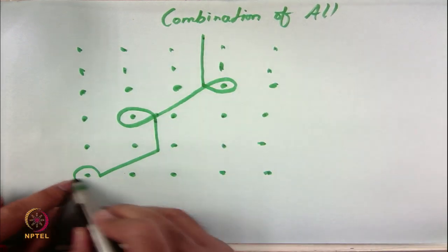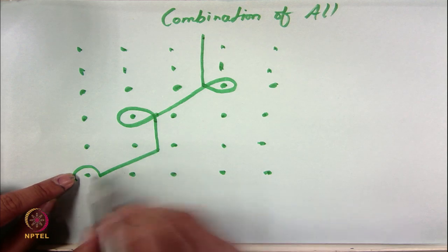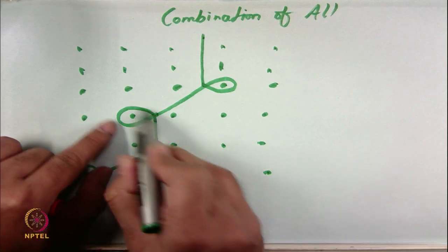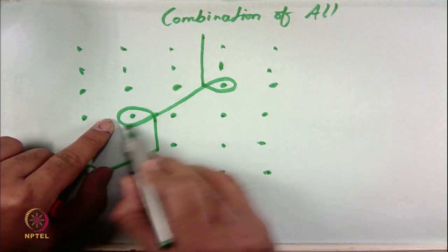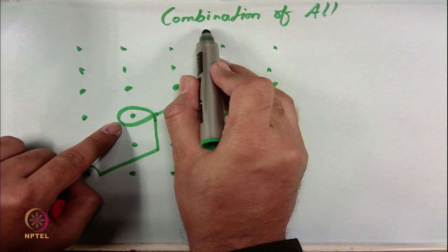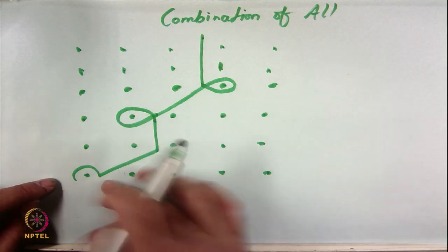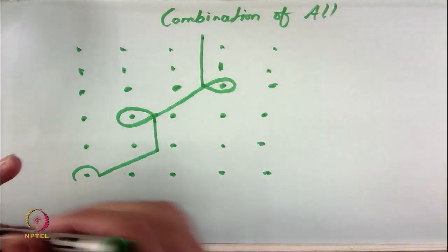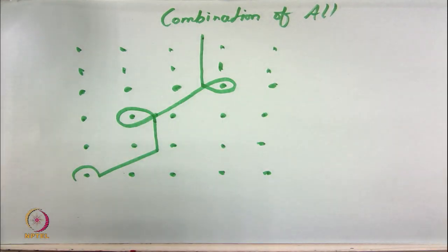Here you can see the overlap and underlap are in the same direction. Here you can see overlap from right to left and underlap left to right. Here you can see only floating yarns. So, each course has a combination of different arrangements for overlap and underlap.